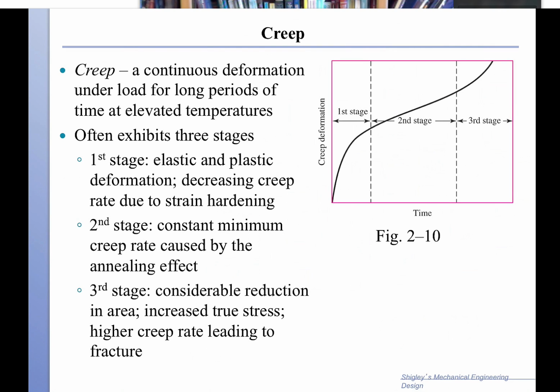With that, we have one more property to discuss, and that is the creep test before we close this segment. So in a creep test, we have a bar, and we apply a load, but we apply the load at very small strain rate. So epsilon dot is very small, like on the order of 10 to the minus 6 second minus 1, for example. So in this case, the material deforms as a function of time.